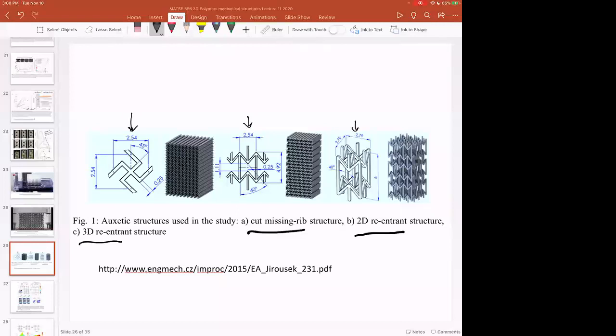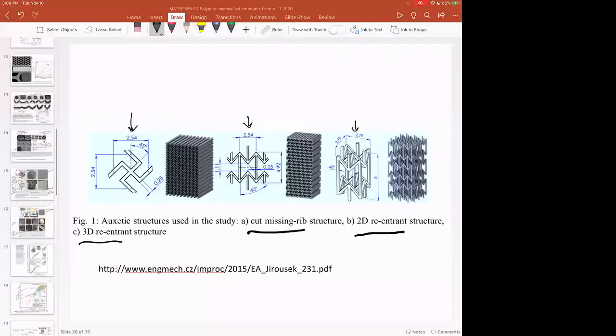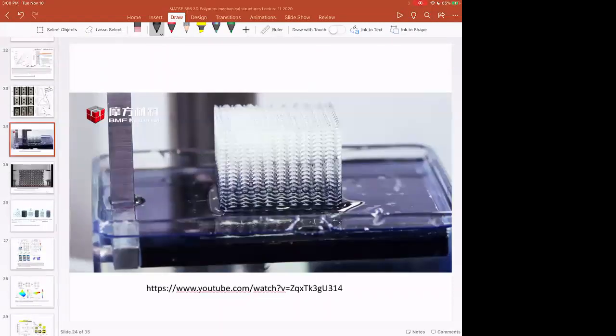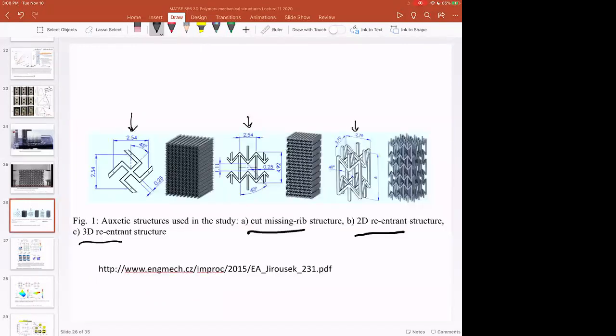We saw in a previous example, and I don't remember exactly where it was, oh, in this video right here, I don't have a picture of it, they printed these elastomer blocks that were flexible in one direction and were stiff when pressed in the other direction. That's a different type of metamaterial, but they all take advantage of these types of design cells. You can imagine injection molding something that looks like this, or fabricating something like this by hand, is really difficult, whereas 3D printing something like this is just like 3D printing anything. You just have to specify the lattice and get your print parameters correct.